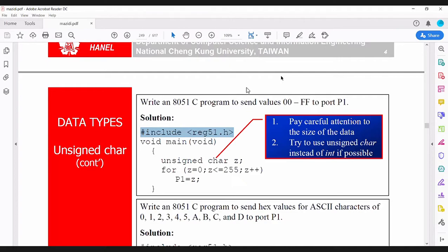You have a library, okay? 8051 has a library. To access this library, you need these header files. That's why he's saying that it's a directive. By writing hash include reg51.h, we are accessing the library files of 8051. If you don't write this,